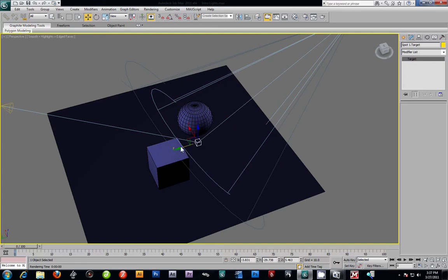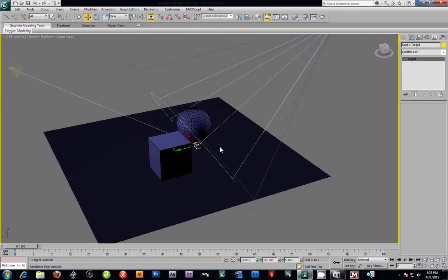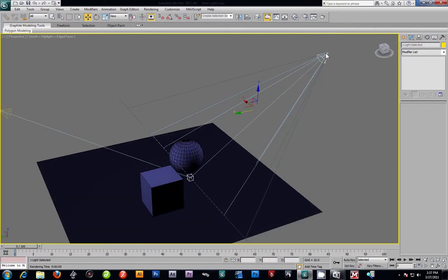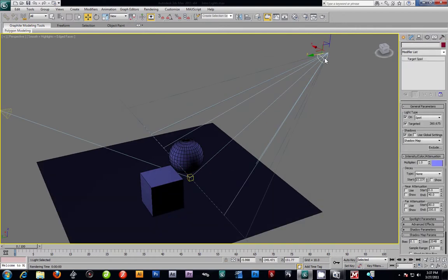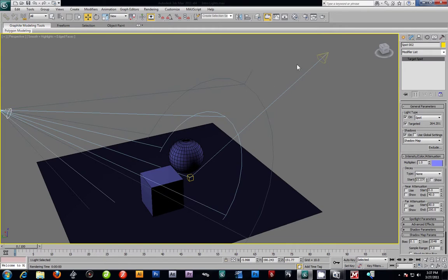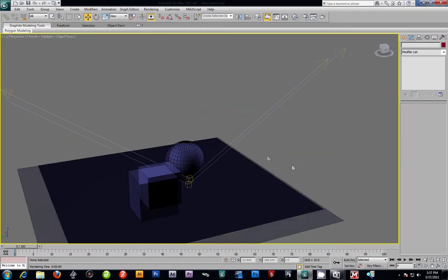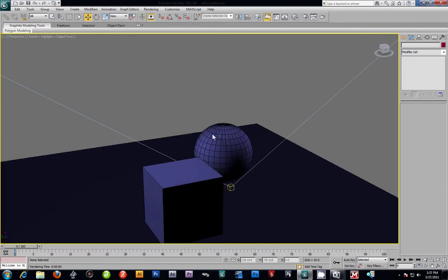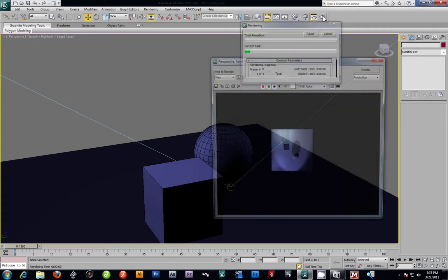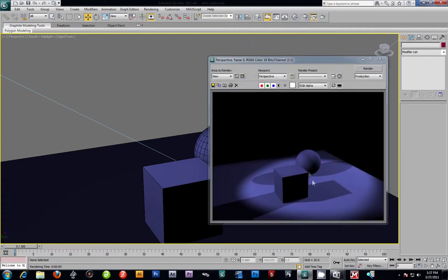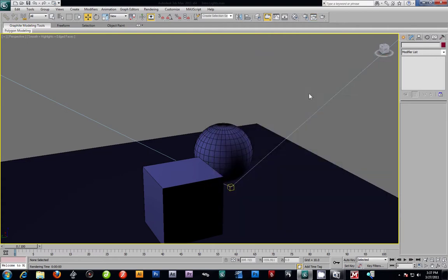So both those two lights hitting together works just the same way as having one light at 2.0. So remember, these are both 1.0. Multiply them by 2 because they're hitting the same area. It works like a 2.0 light. And that's how it is for all your lights. If they cross paths, you have to remember it's multiplying the area it's hitting. So if I render this out, that's a 2.0 light.